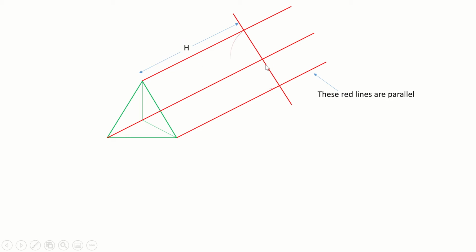The next thing we'll do is just draw an arc, and the center point of the arc is here, as you can see. It's located between the two extreme points. So the next step is where the arc intersects the middle line here, we're just going to draw a point, and you can see here, you're going to project your lines as shown.